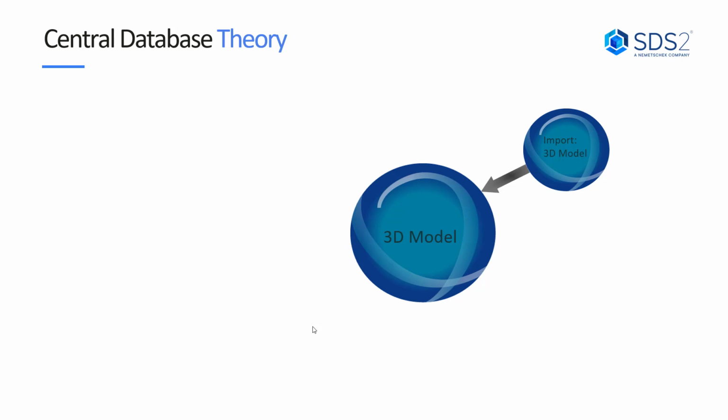There's some more file types that you can bring in as well, and we'll take a look at this later on in the course. You can also use a tool called parametrics, which are basically a script written inside of Python that can be run within our modeling window. Using parametrics will allow you to do things like add material, add members, adjust members, and perform other repetitive tasks. We will do some work with parametrics later on in the training.